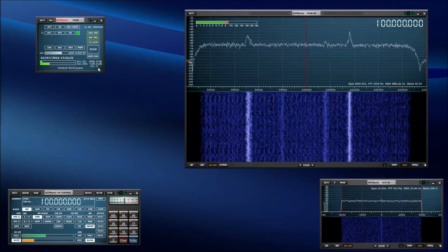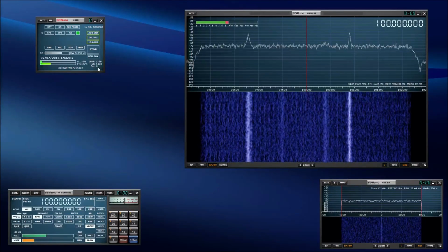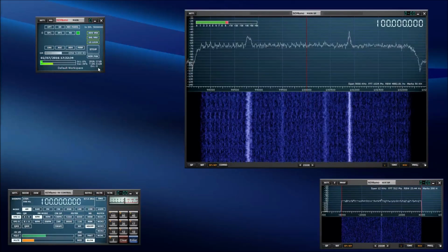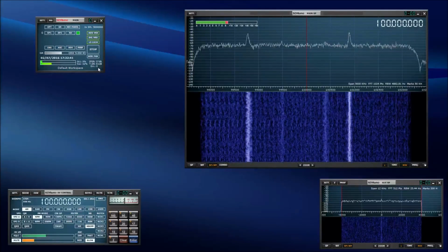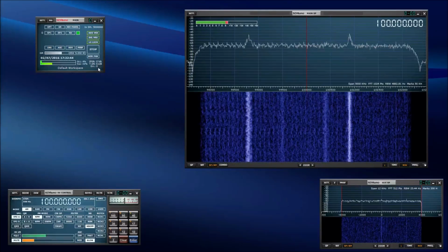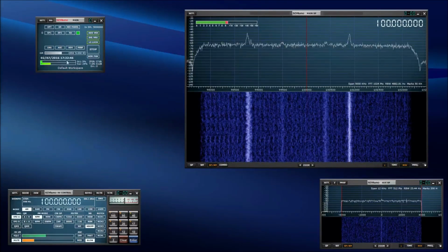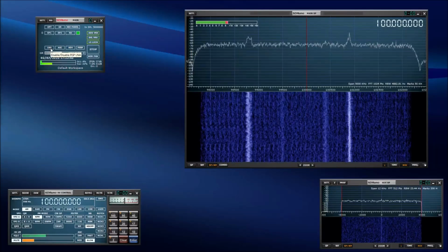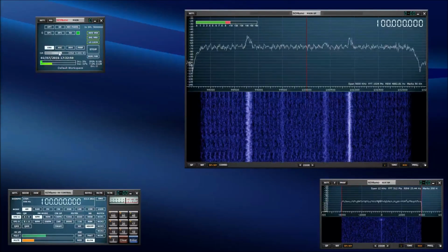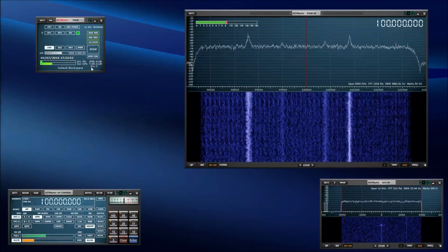So we did that differently. Now when you turn the LNA on and off, there's a compensation made such that the total system gain remains the same whether the LNA is on or off. And that makes it more usable when you are using the AGC.